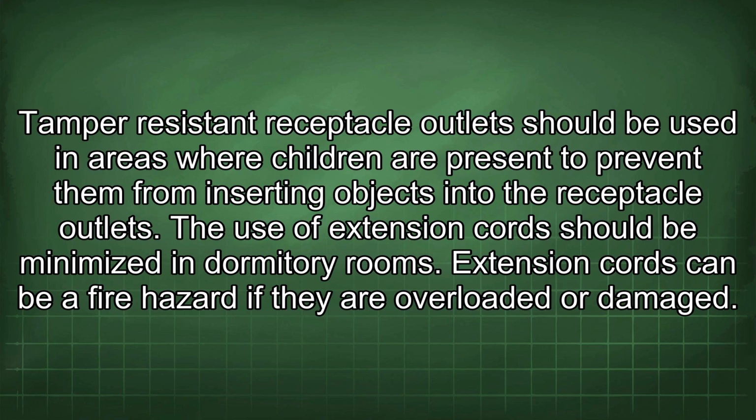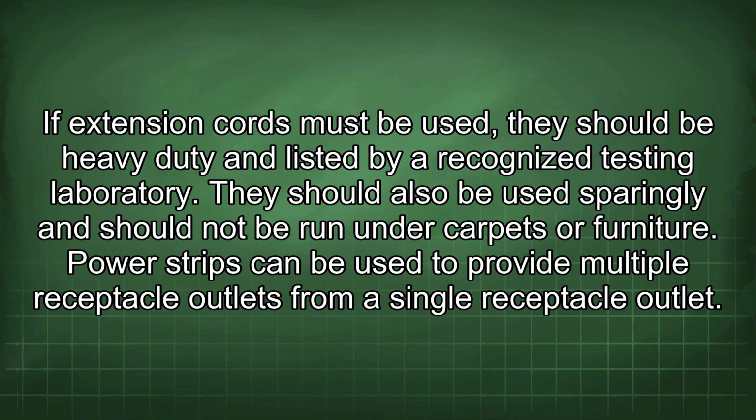The use of extension cords should be minimized in dormitory rooms. Extension cords can be a fire hazard if they are overloaded or damaged. If extension cords must be used, they should be heavy-duty and listed by a recognized testing laboratory. They should also be used sparingly and should not be run under carpets or furniture.